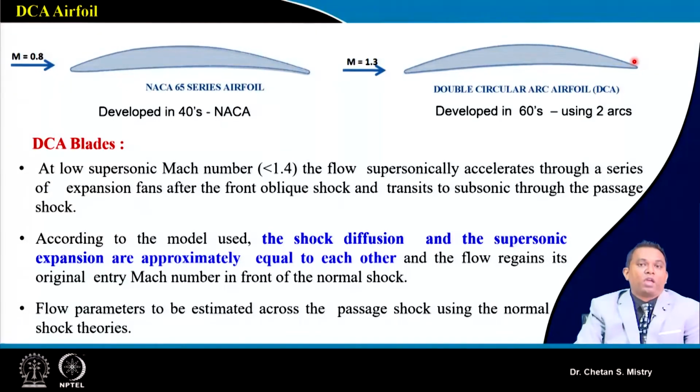We are looking for our flow not to be very sensitive to sharp edges. Here in this case, my flow will behave nicely on the suction surface as per the expectation, and later part also it will give diffusion.